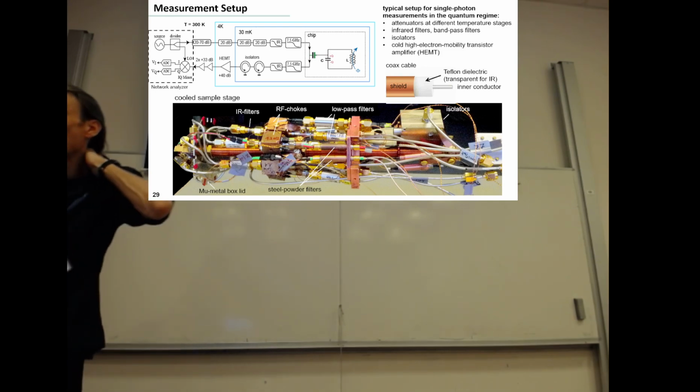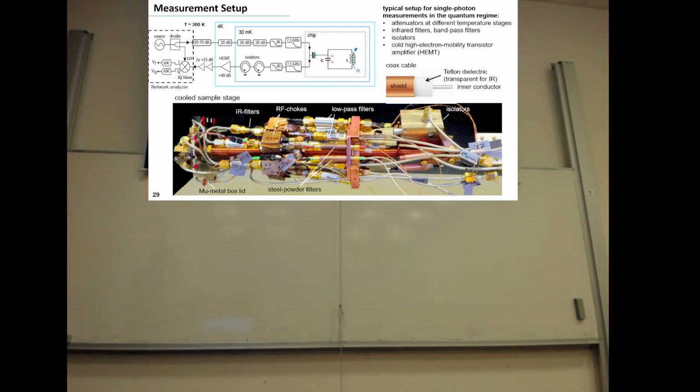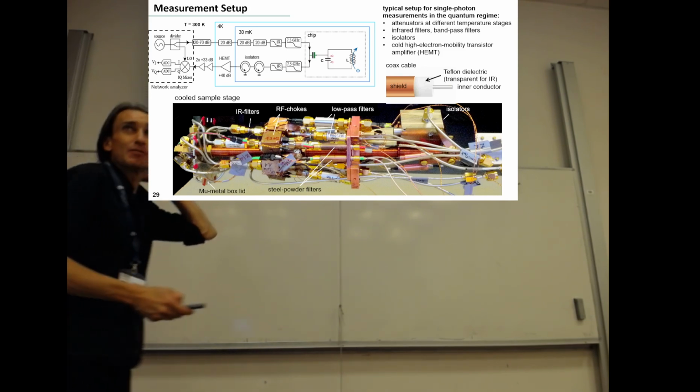Yeah, and then the solution is of course just to put some infrared filter there. You can see one of our versions here. This is just another piece of coax cable. We have replaced this Teflon dielectric with just some dark epoxy, some black epoxy, to shield this.